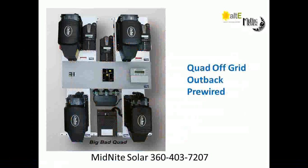Picture of a quad off-grid system. As you can see there, this has 4 inverters, 3 Classics, a Mate 3, of course the hub, and this box down here is the PSX 240, which is an auto transformer. What that does is it allows one inverter to make the 120/240, and the other 3 can go to sleep until they're needed. So you save a lot of energy on idle losses of the inverters sitting there just running for no reason. Again, this was built as seen and shipped out on a sheet of marine grade finished plywood, so it was ready just to hang on the wall and plug battery cables and AC in and AC out to.